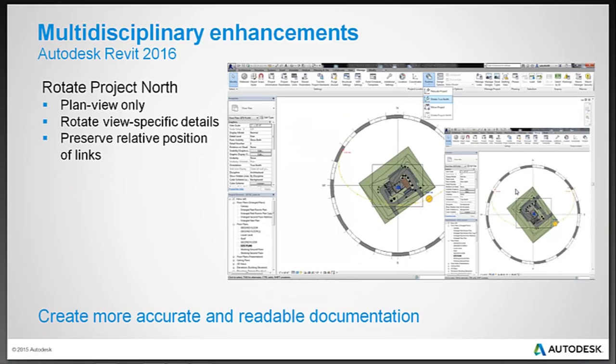We can now rotate project north. In addition to rotating model elements, this tool also rotates view-specific detail elements, including text notes, detail lines, filled regions, revision clouds, and more. This will affect the model elements and view-specific detail elements. It will also preserve the relative position of links. This will rotate decals applied to surfaces and affects plan views whose orientation property is defined as project north.